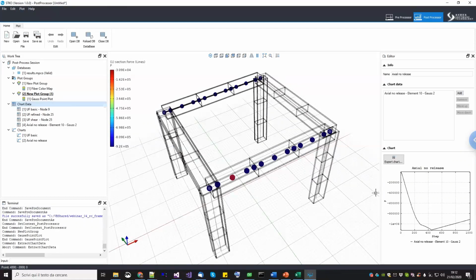Finish. Now as you can see, we are working in Newton. So you start the analysis with almost zero normal stress here, axial stress. And then as you go into the nonlinear behavior, following the hardening part, you even reach 1000 kilonewton, which is something that you do not expect on this kind of beams. Actually, this one is much more than the total vertical load that you have on columns here. And then only when you have some softening, you start having a decrease of the axial stress.